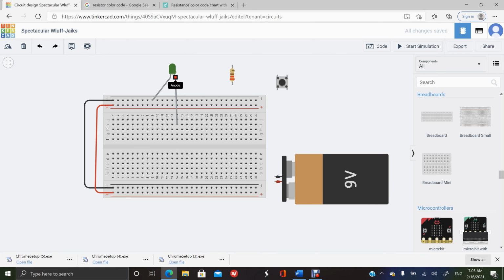Okay. You need the resistor in series with this LED, because for the LED we're using 9 volts. Okay, and an LED has some kind of voltage rating, approximately about 2 volts. And if you put a high voltage on this LED, you can really burn it. Okay, when I say burning, you're not going to make fire, but it's just not going to work. So let's choose a value. Later on in the workshop, I will talk about Ohm's law and how you can actually calculate the value. The value here is not right, but it will work. Let's keep that value for now, and later we'll talk about the resistor.